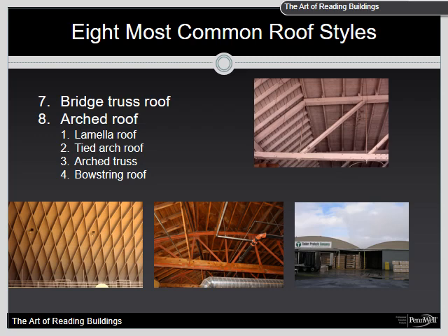Strengths. This type of roof uses a large size of lumber and planks as the roof sheeting. The strongest area of this roof is at the perimeter of the building. Hazards. The primary hazard of this roof is early failure of the metal tie rods and turnbuckles. The tie rods provide lateral support for exterior walls and prevent the arches from pushing the exterior walls outward, thus thwarting collapse. Because this roof depends on the strength and security of its tie rods, failure may occur in sections that are exposed to fire.